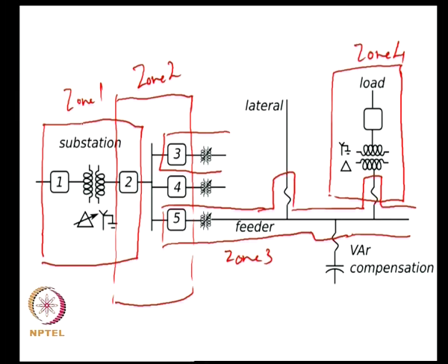For example, you might put a high end protection relay with circuit breakers in a higher zone, whereas you might want to look at something more cost effective, maybe just a fuse and some arrestors for low voltage protection at the other end of the zone of protection.